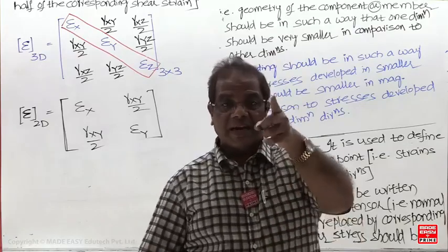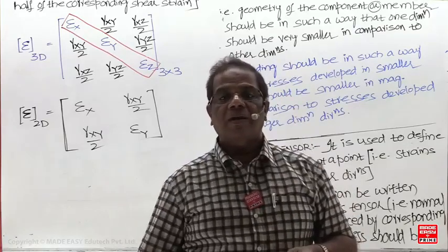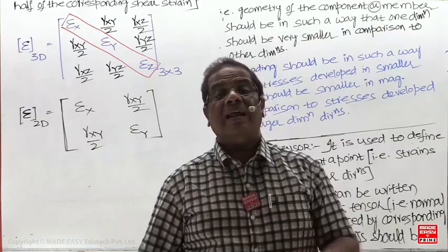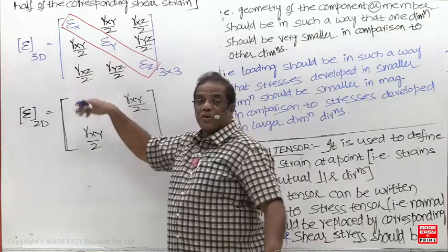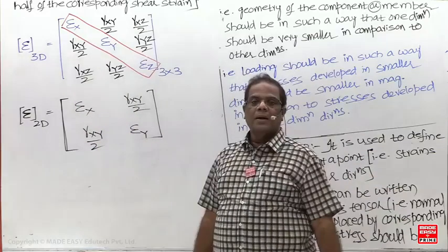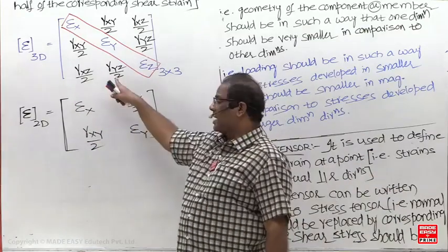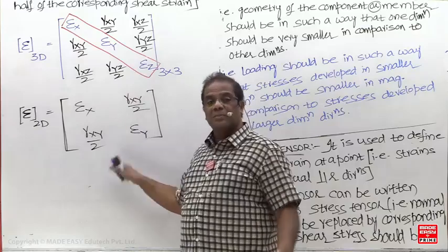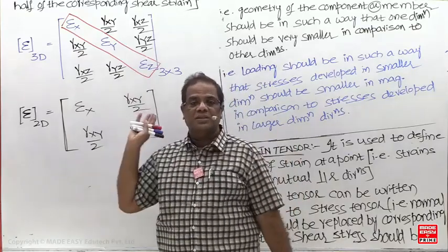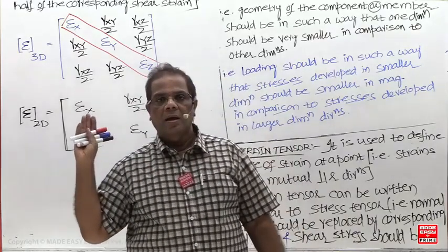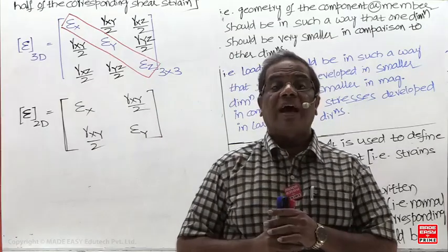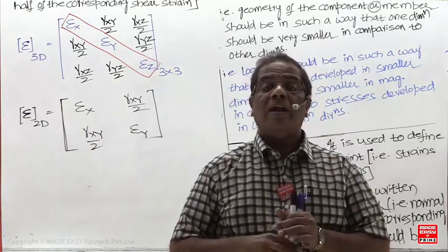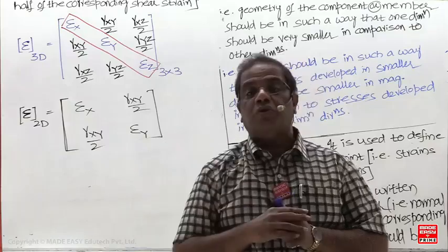For the plane strain condition, what is it? Whenever you want to assume a triaxial state of strain, assume this is the triaxial. If you want to assume the biaxial, when the actual problem is triaxial, then what condition have you studied? Stress in one of the directions is very small in comparison to stress in the other two directions.